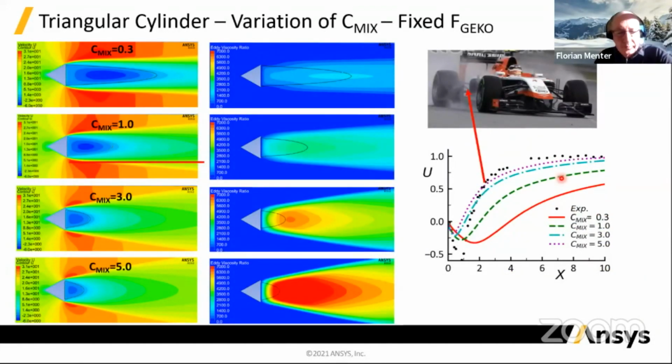Now here's another interesting problem that we often face. It's a flow behind bluff bodies. And of course, in reality, what you have is vortex shedding here. You have a turbulent von Karman vortex street here, which at least in its initial stage is an unsteady phenomenon. It's not really a turbulent mixing, but it's an unsteady mixing from the flow flip-flopping from one side to the other. And in reality, you should do that with an unsteady simulation. It's not something really any turbulence model is tuned to capture.